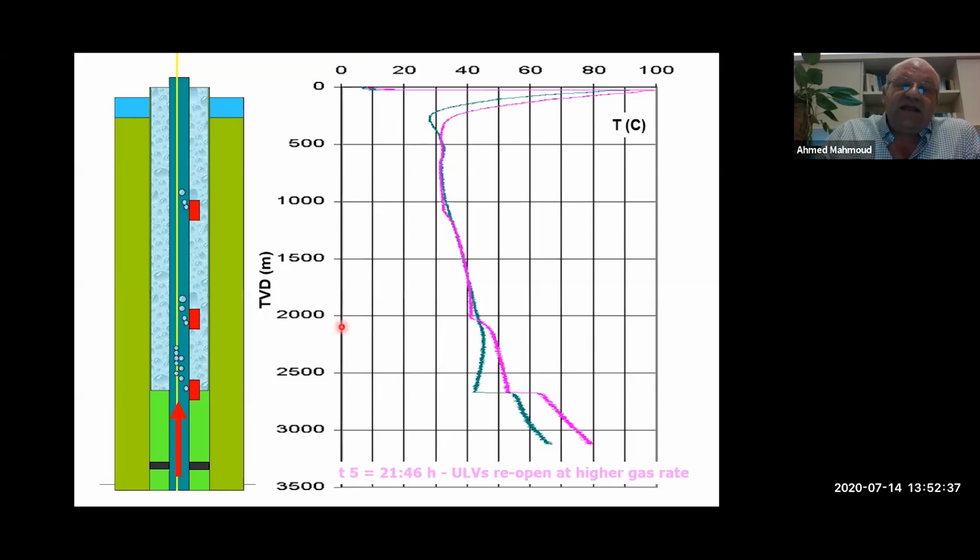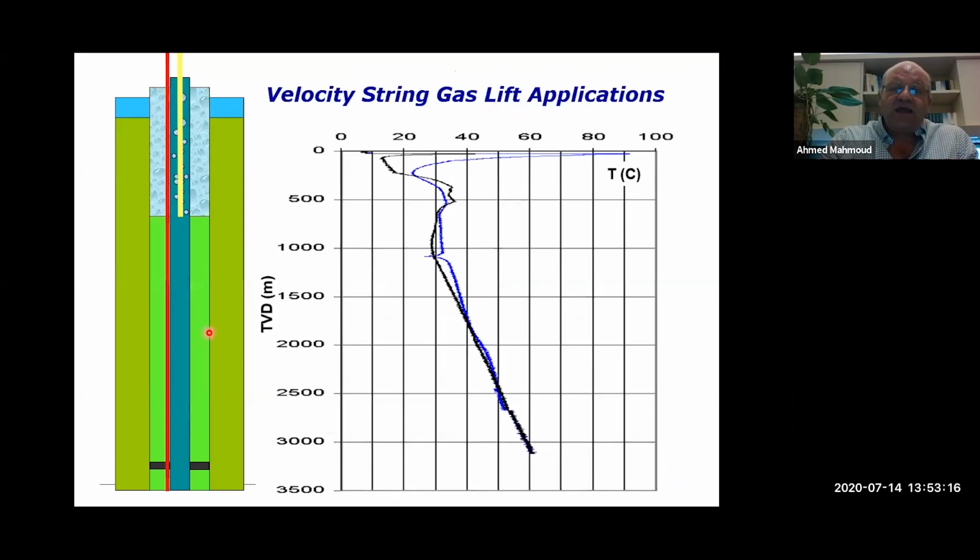All right. If we take a look at this example, here this valve is working and I can sense a big kink here across the valve, which is okay. It's a good sign. And then I have a kink here and another kink here in the temperature survey. And this is not good because this means that I have these 2 valves leaking. These valves should be closed when this valve is operating, and this is where I have already troubleshooted the system. I know that these 2 valves are leaking, and you can ask Slickline to come and change these valves with better valves. Okay. All right.